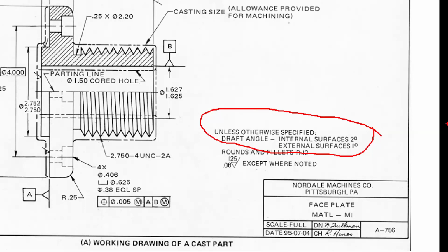As it opens, again, the slide comes up, and then ejector pins push the doodad out. If you've got any toys at home still, primarily easy, cheap plastic toys, look at them close. I'll pass it around in a minute. You can see the parting line usually. You can see where the gate was broken off and maybe sanded a little bit. You can see a little spot where the material came in.